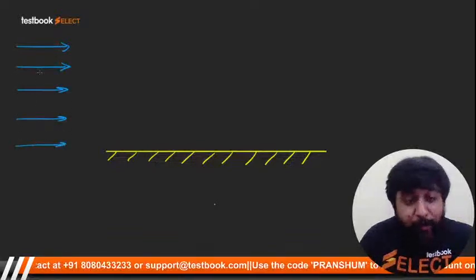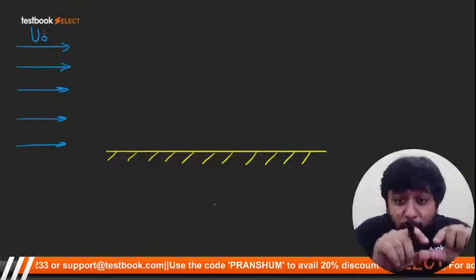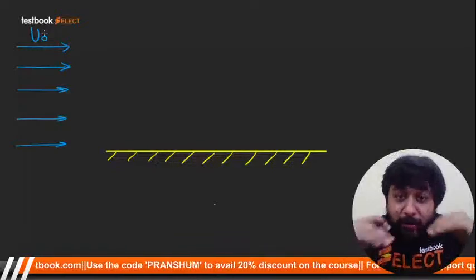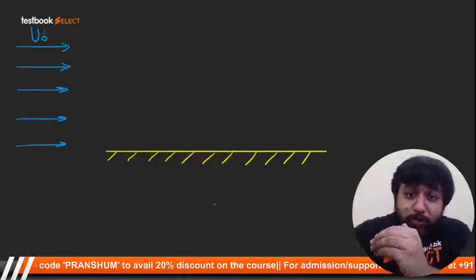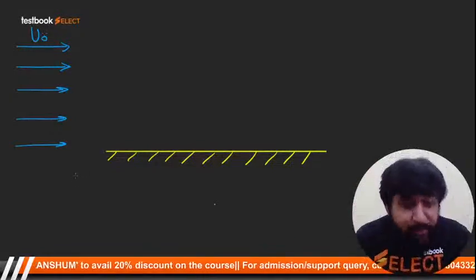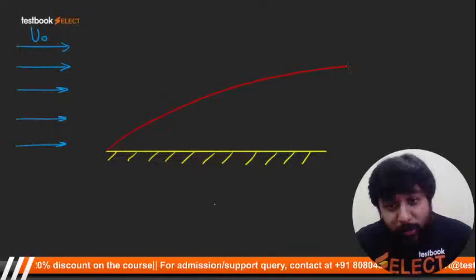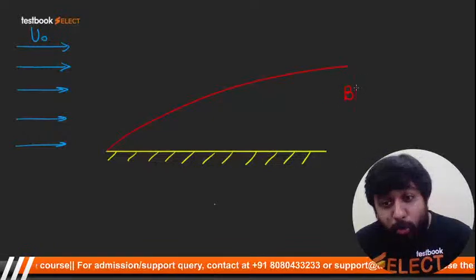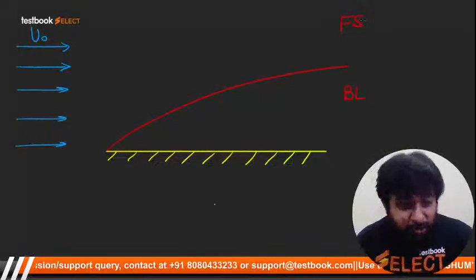So what will happen? As soon as the fluid reaches the surface, the bottommost layer of the fluid will stick to the surface. This bottommost layer will slow down the second layer, and the second layer will slow down the third layer. As a result, we will see an imaginary line. This imaginary line divides the flow field into two regions: one is the boundary layer and the other is the free stream.